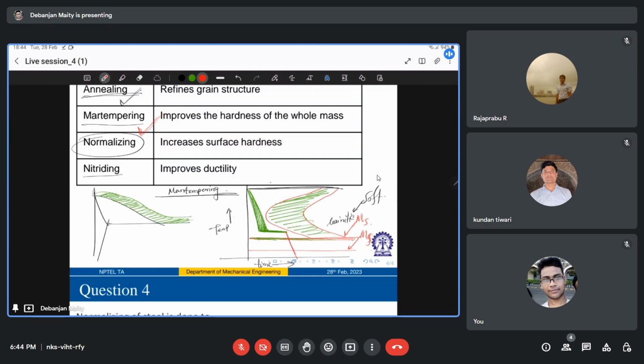Then you are cooling it in air. Correct? So this is your martempering. This basically illustrates the difference of temperature distribution on the component during quenching in water or oil and in the molten salt bath. Have you used this to understand what the difference is? Okay.